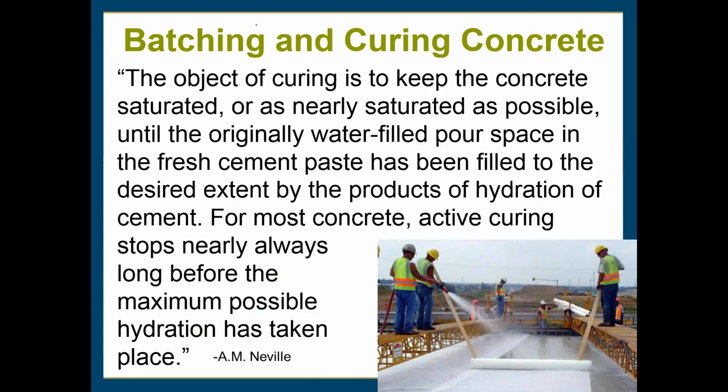Additionally, moist curing is mentioned here. You'd like to keep it moist and provide enough water for the cement to hydrate as the water does evaporate. Because when concrete doesn't dry out, it's curing. The cement is hydrating. The water in your mix is not drying out necessarily. It is being consumed by that hydration reaction. It's not just all evaporating.